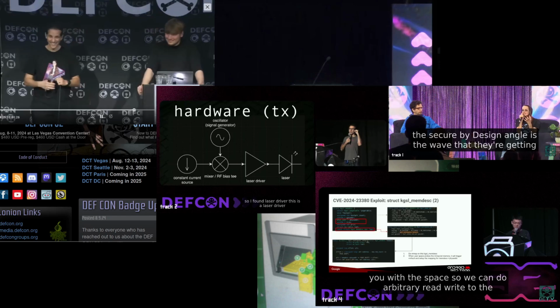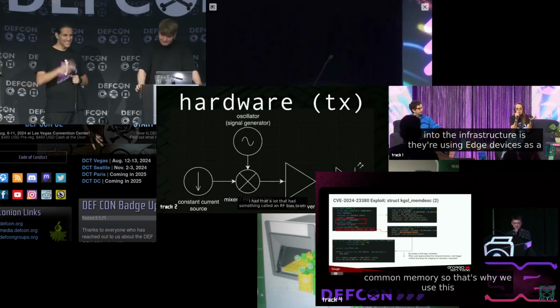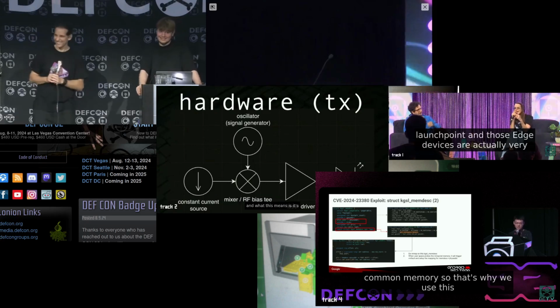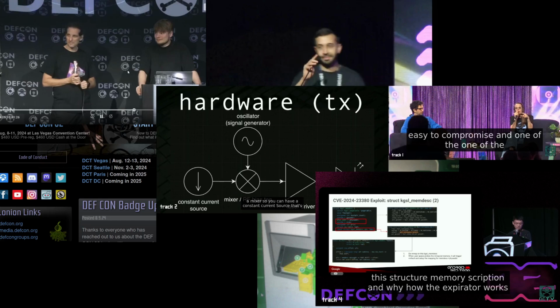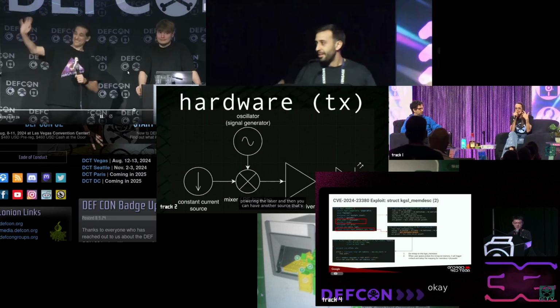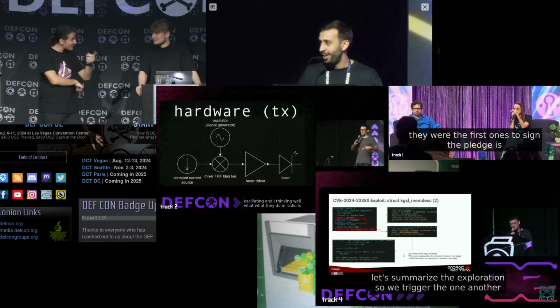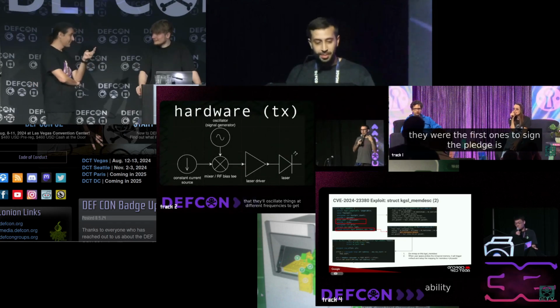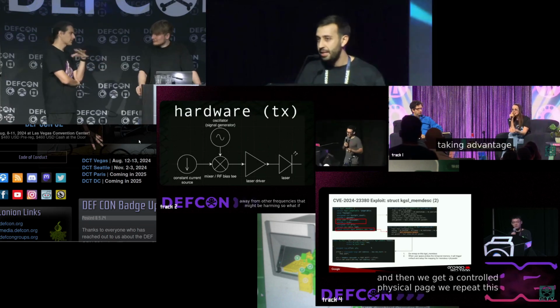You have a laser and you point it at the window. Every schematic, every laser microphone I've ever seen simply has a constant laser source, hitting something and reflecting back. The problem I found with this is that there's so much noise. We have the 60 hertz noise from the wall. We have all sorts of noise from computers around. And all this stuff is typically low frequency noise that's messing with your signal. And we need to get rid of that.